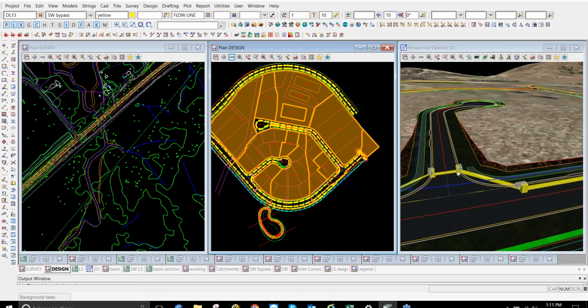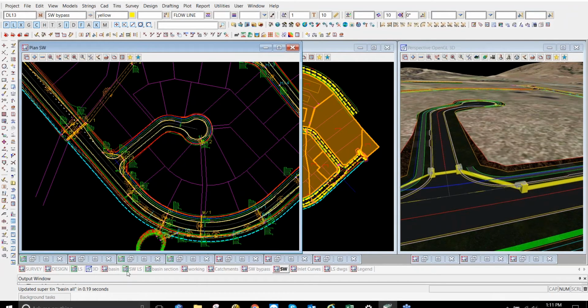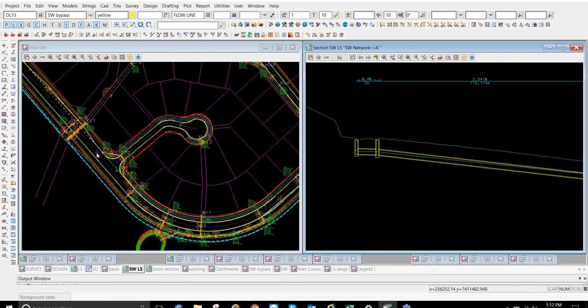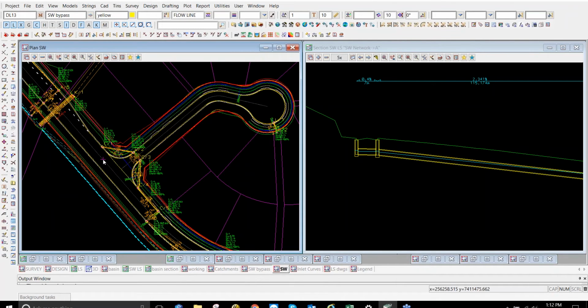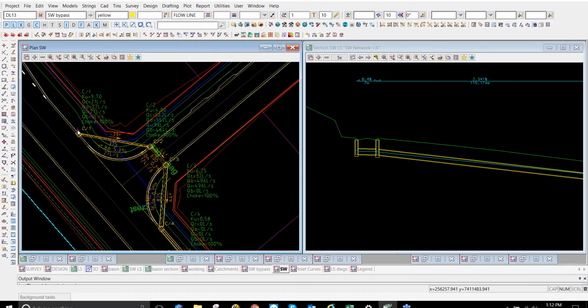Now to talk just a little bit about the stormwater design inside 12D. I'm just going to switch over to another view which has my stormwater on it, and bring over one that's also got my long sections on it. So when it comes time for the inlets and the pipe systems, or open channel, whatever you're putting in, because Sophia mentioned the many different components of a waterway system, the original structures, probably the easiest way to create them is inside 12D, because you've got your roadway center lines, you've got your curb inlets, you know exactly where these structures are going to go.